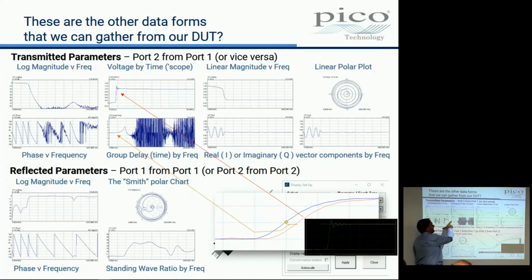That's that 2 nanoseconds. That's on 2. I don't know whether you can see, that's 0 and that's 2. It's measuring a group delay of 2 nanoseconds at low frequency. In other words, all low frequencies are delayed by 2 nanoseconds. Now, this is interesting. As frequency goes up, the signal gets delayed a bit more.